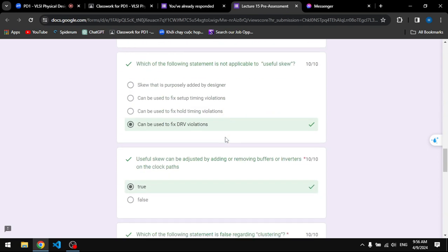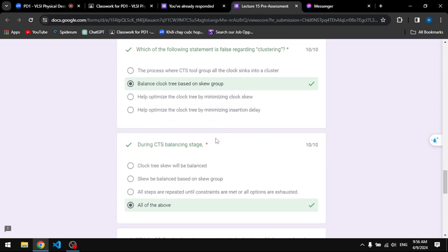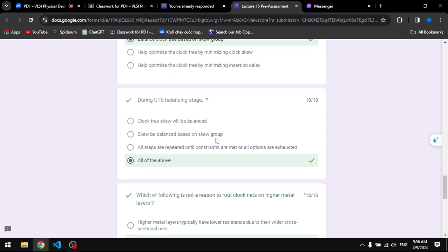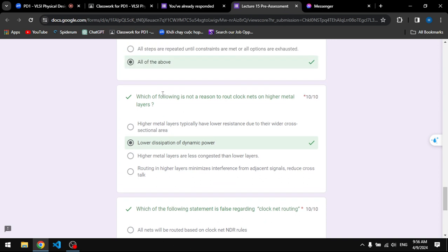There are two types of load splitting. You can see here buffer A is driving 4 buffers B. Let's say there's too much load on buffer A. We want to split this load, meaning cut it in half. One method for load splitting is called cloning, and you know what cloning is.